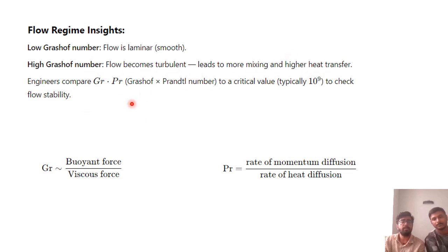And to compare the momentum diffusion and heat diffusion, and how the flow is happening, the Prandtl number will basically tell us the flow regime, as it is the ratio of momentum and heat transfer. So combining these two equations, we will account for both heat transfer and momentum transfer along with the velocity profile. And from here, we could get the temperature profile.